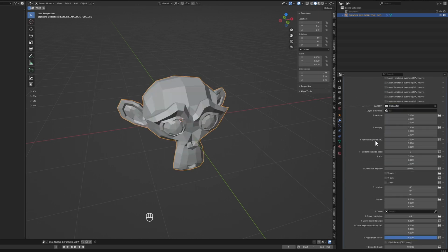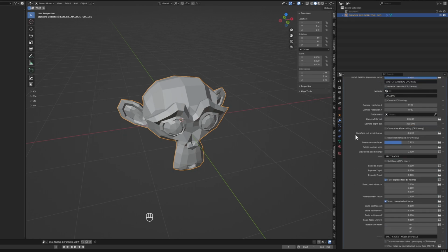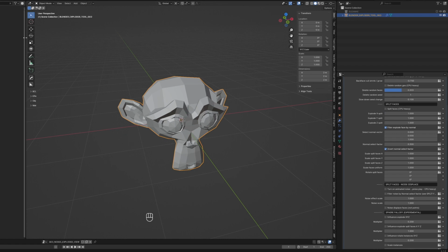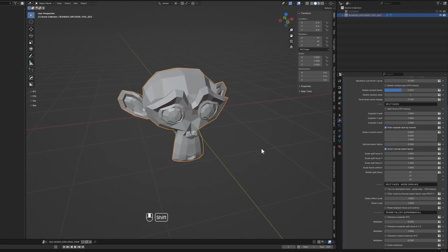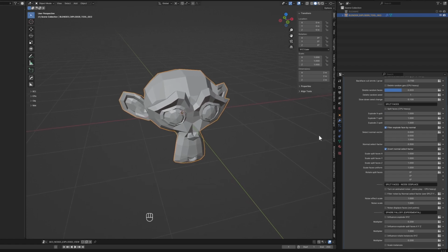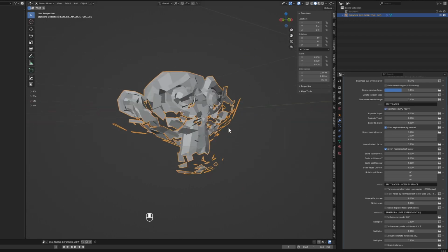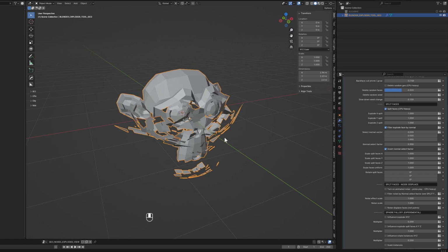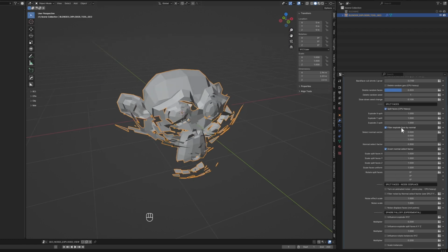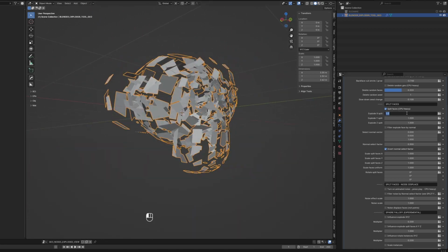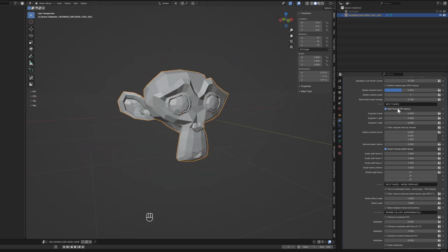Just pick a layer and select a collection like so. And then navigate to the Split Faces section, which, of course, first you have to activate by this checkbox, and you see some faces of the mesh get exploded, but not everything. So let's just, for now, turn off this filter right here so that everything gets exploded equally in all directions, and now it does.